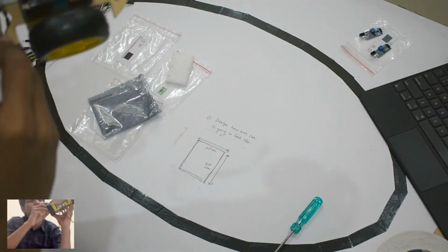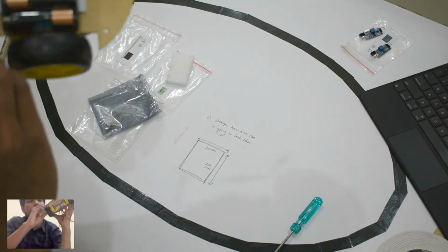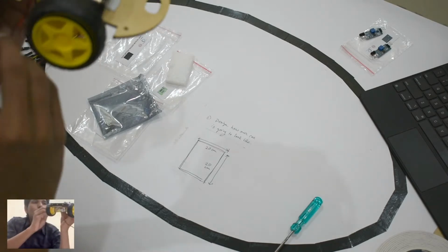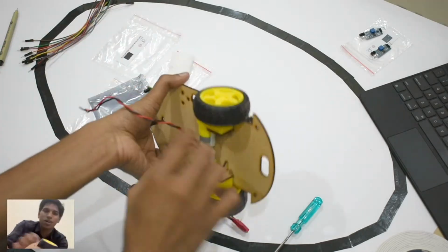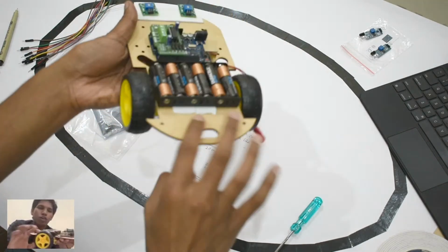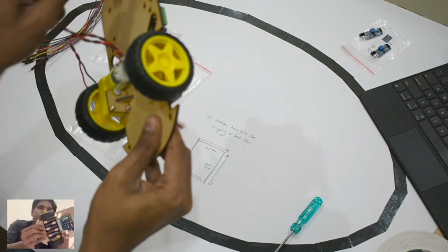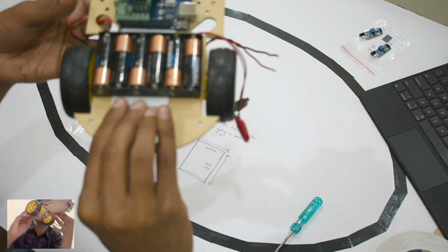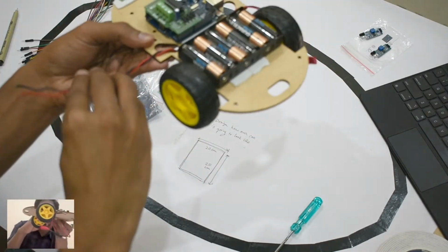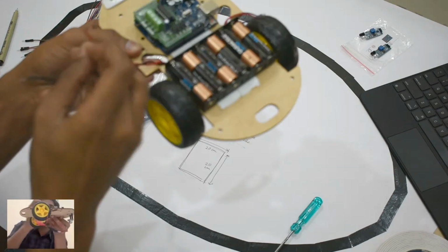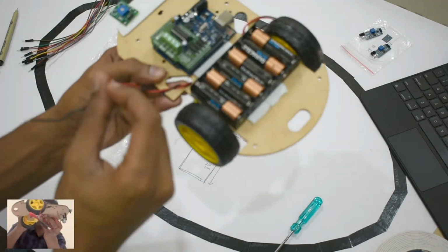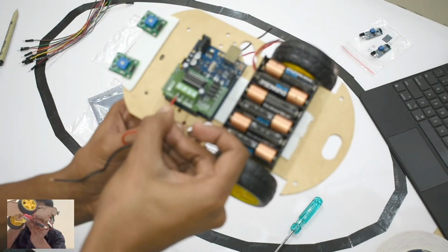So now I have these pins here. These are connected to these pins here. They are numbered the same as these pins. They are numbered 2, 3, 4, and 5. So I will know that when I connect, let's say this is the left motor of my car. I'm going to bring out its wires. And now I'm going to connect the red one, the red one that I know will make my tire move forward if I give positive supply to it, is going to be connected to pin number 2.